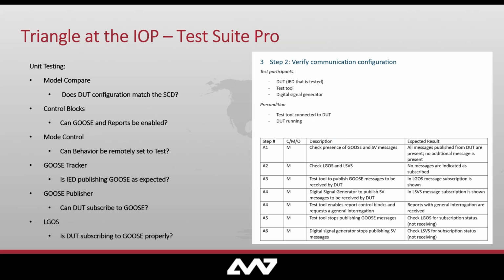We use several features within Test Suite Pro to ensure that the device under test was properly configured. So for example, Christoph mentioned earlier the model compare feature. This would allow us to verify that the device actually had the correct configuration, that the right or matching SCD file had been loaded in for the prescribed test.